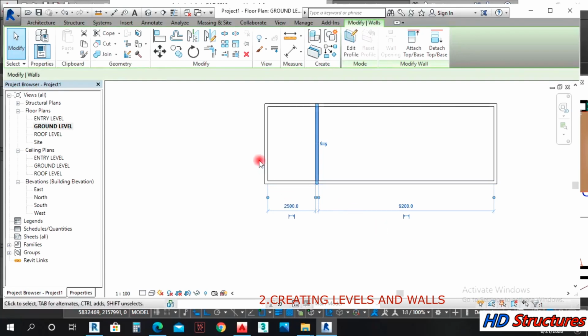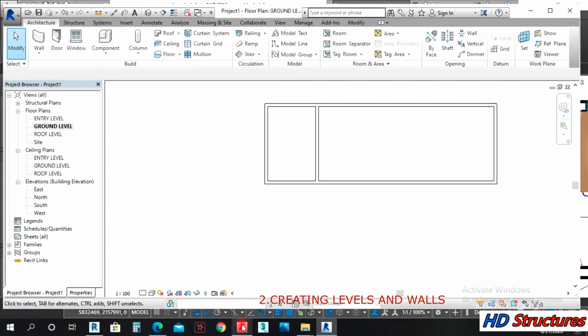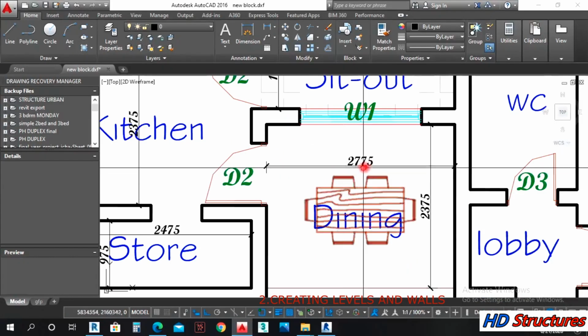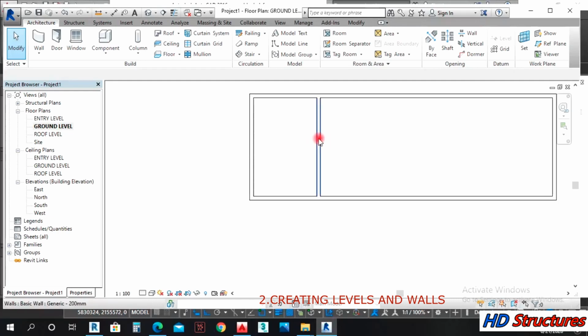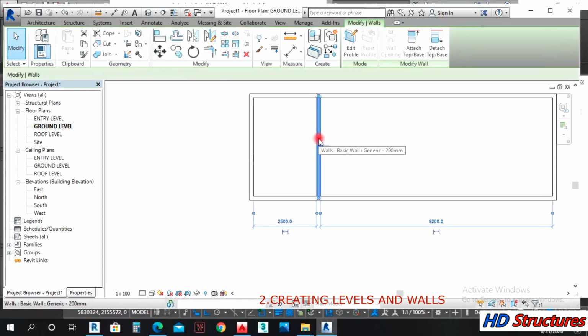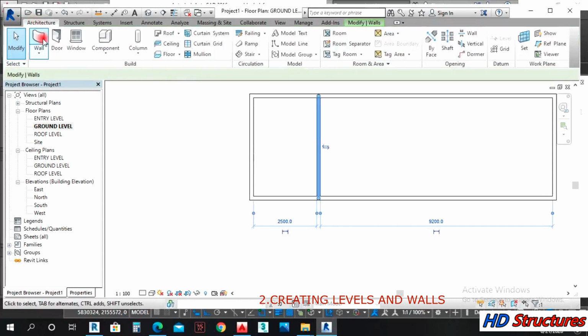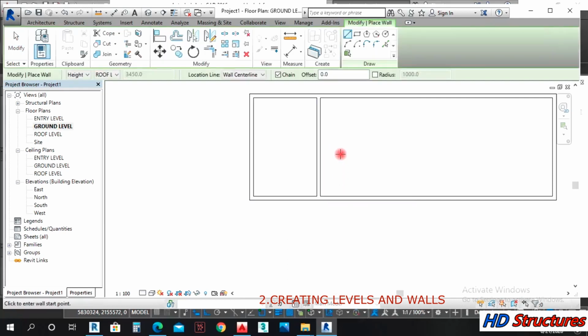But let's say I have decided to change this thing to be 26. Okay, let's proceed. Let's go to the next wall first. So this one is 2,700. Let's come back here. We can left click this wall. Want to draw a new wall? You can either come to architecture and start again and left click again, or you left click this very wall, right click and create similar.